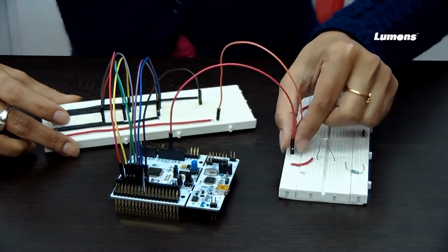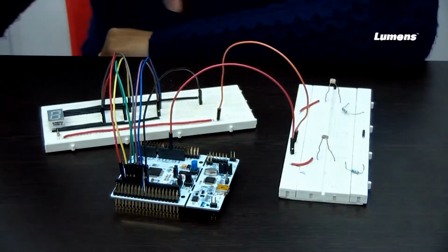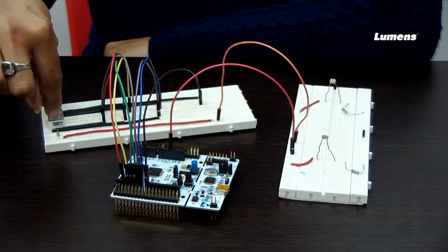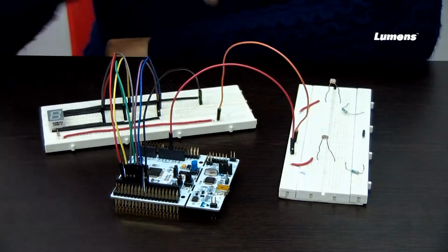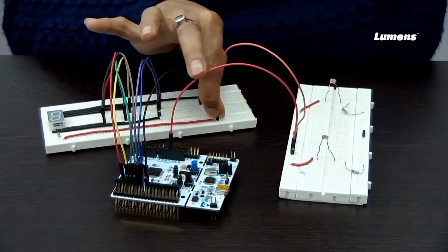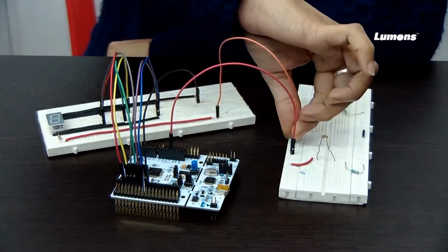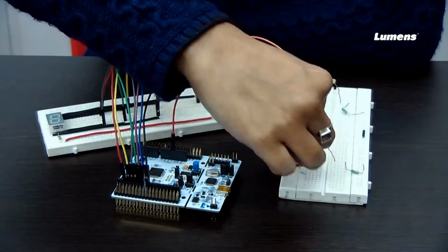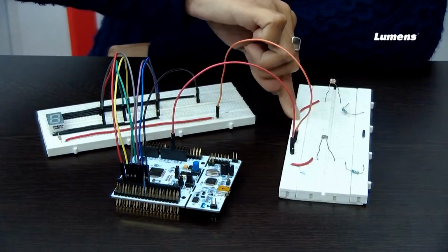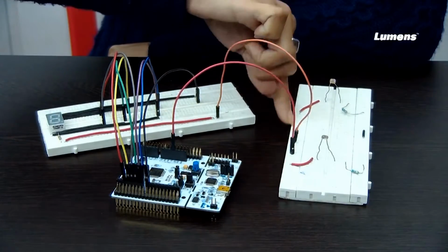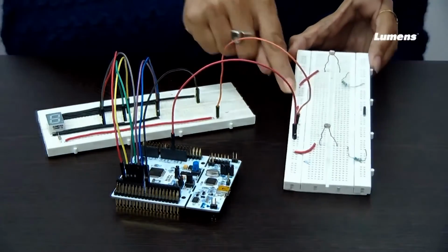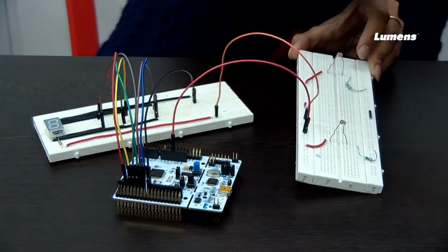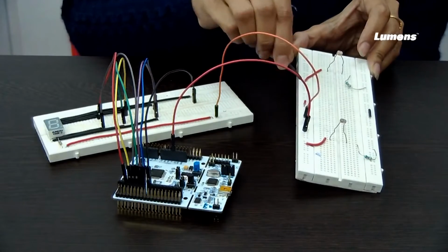I believe the connection is clear to you. This we already did earlier. So from the common point, this is the common point of the 7 segment, we are taking this and connecting it to the VCC, and this is 5 volt. I have connected to this point. So we can use this whole set of lines. All are connected because, see, in the middle I have made this connection. So from the middle it is also connected from here till here.